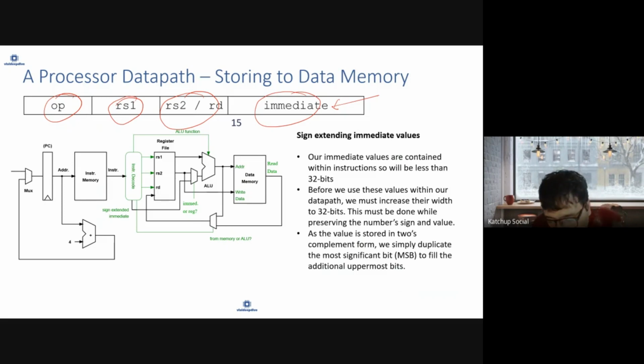And we had said, you had to notice this was 15-bit, this was 16-bit, and our normal operation is 32-bit. So in order to use it, you have to sign extend this immediate value. Here you're selecting whether you are reading from immediate or from the register file. If you're reading from the register file, the data will come like this. But if you're using immediate, the data will directly come from your instruction code decode. So you can choose, and that will go into your ALU operation.